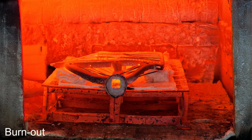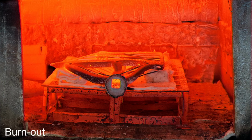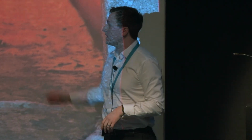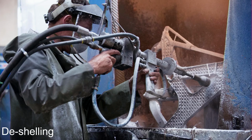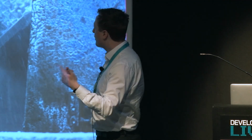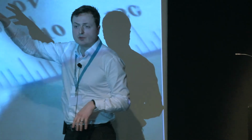This is where your choice of design and material that you use for your pattern is very critical. If you have a plastic that expands too much, it will crack that mold. So you need something that's not going to cause that mold to fail. And then we're pouring in the material. In this case, we're pouring in magnesium. So that component you'll see on our stand is made from magnesium. And then we've got a D-shell. So this is where you've got to be careful with lattices. You can cast maybe 1 or 2 cells thick in lattices. Start going more than that, then D-shelling becomes difficult. So you end up with the shell stuck in the middle, potentially.